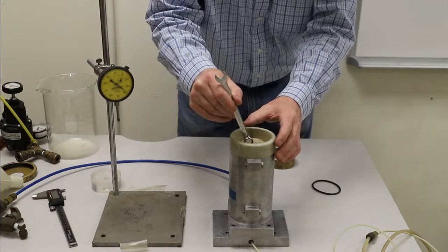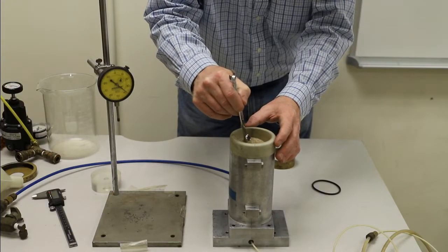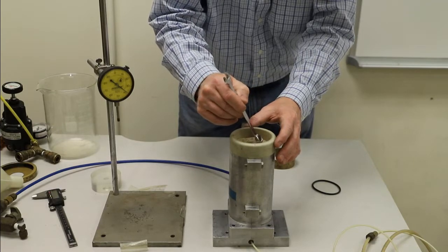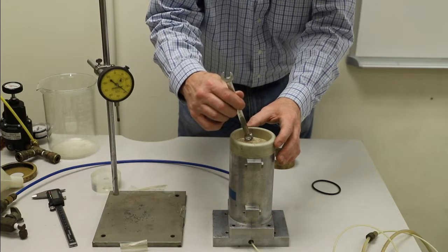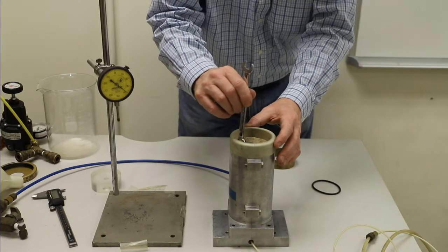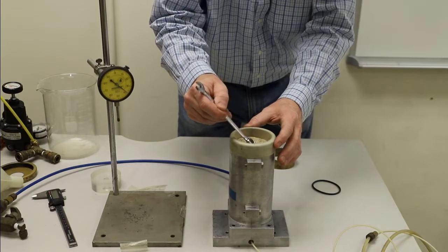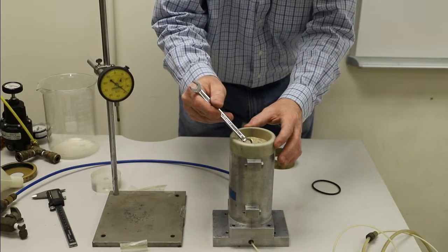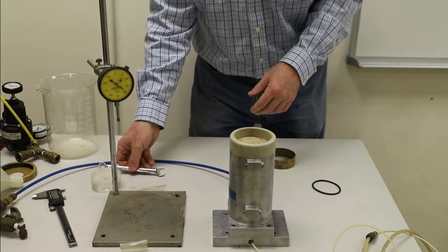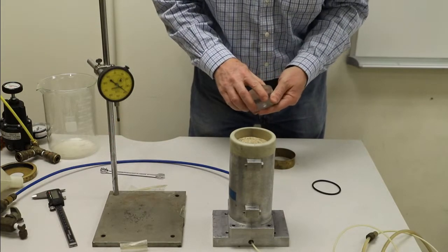Again, I want to apply as little energy as I can, and I probably should just recognize that in shifting this sand, I'm probably densifying the sand right at the top cap a little bit. Okay. Now that shouldn't affect our strength measurements very much, because the soil that's right against the top cap and right against the bottom cap are protected from shearing anyway in a compression test. So we might have some small effect on the measured density, but shouldn't be a big deal.